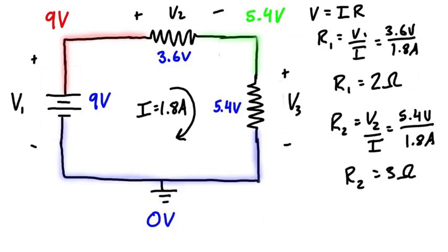And that's the point of Kirchhoff's voltage law. If we came back and ended up with something that's not 0, then this wouldn't make any sense because this can't be two different voltages at the same time. So you have to come around the whole circle and return to the value that you started with, and that's basically the same as saying that the algebraic sum of the voltages around the loop is 0.